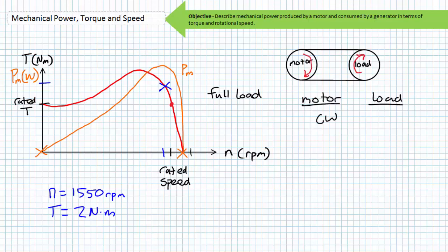Let's get right to the point about polarity. If a motor spins in the clockwise direction, it produces clockwise torque. The opposition torque is counterclockwise. If a motor spins in the counterclockwise direction, it produces counterclockwise torque. The opposition torque is clockwise. In both occasions, however, we've got to say that this motor is producing positive mechanical output. How can we use a polarity convention to make this a reality when 2 different directions produce positive mechanical output?